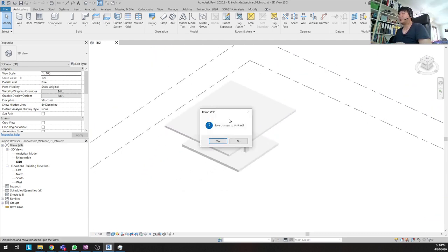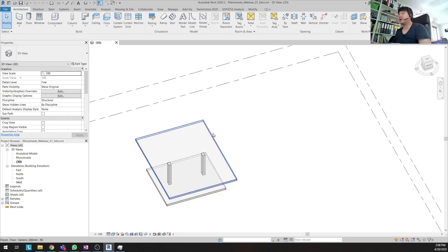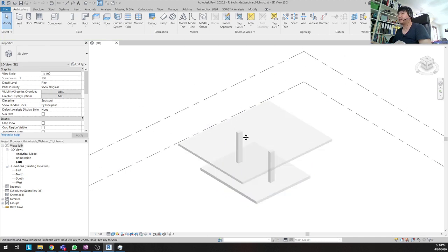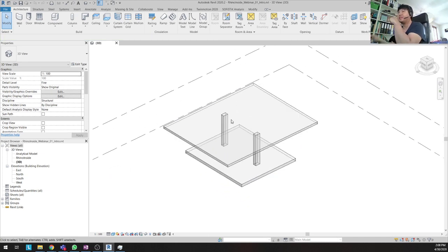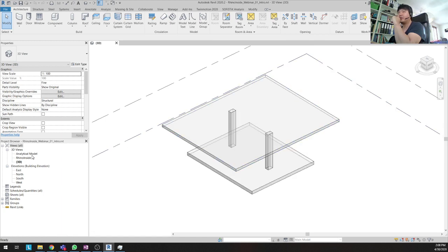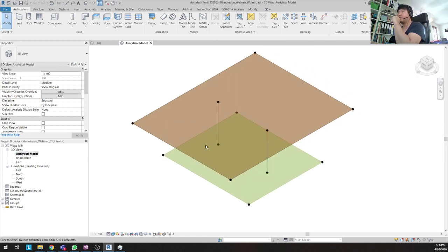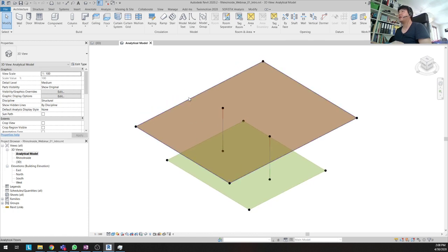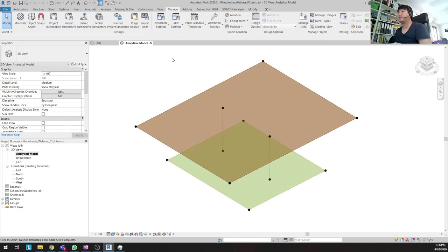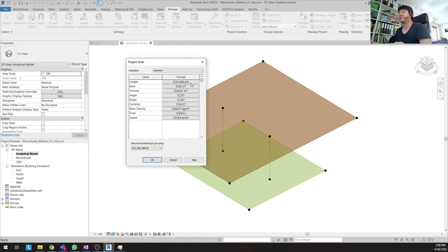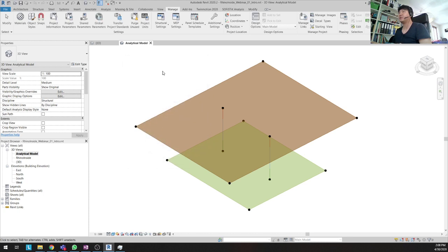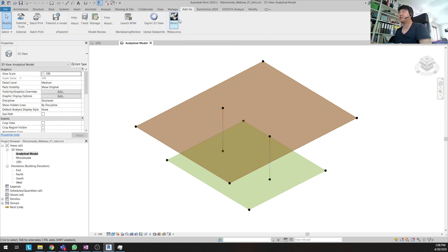Last week I was showing basically how we could convert Revit's existing model from the analytical model to use in Karamba3D. Again, before we initialize Rhino.Inside, it's always good to check your project unit in Revit. At the moment, I'm using meter for this example, so I'm going to click on add-ins, and to initialize Rhino.Inside, click on Rhino.